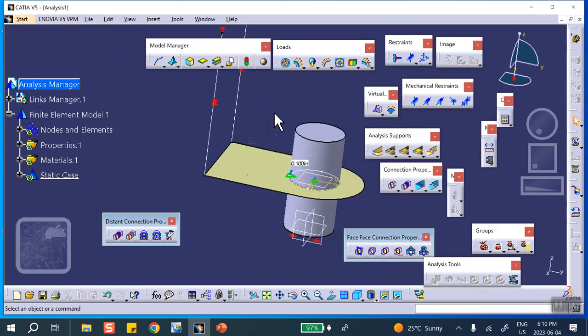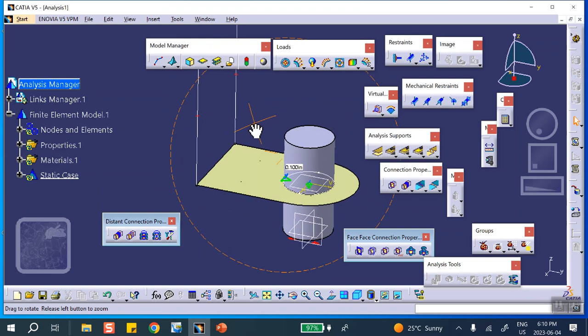It said if I run this thing, it's going to bomb out. You know that. Please watch the video from yesterday's lecture, because you need connections. Point to point, bottom of this line and the corner of that surface. And again, bottom of this other line and the corner of that. And these connections must be rigid. Point to point is rigid.